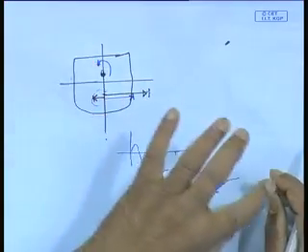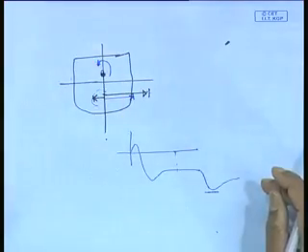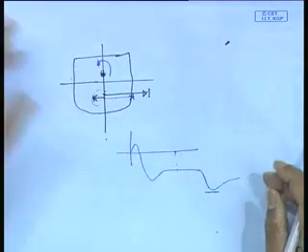Just imagine that if you are turning and heeling outward, and then everybody also moves outward, then there is a further shift of weight outward, and then a free surface effect, water moving to this side. That causes further augmentation of the problem because you are moving outward. So this is an important point: when we talk of safety during a turn, the heel becomes very important. But we will find out that for large ships the heels are very small angles.